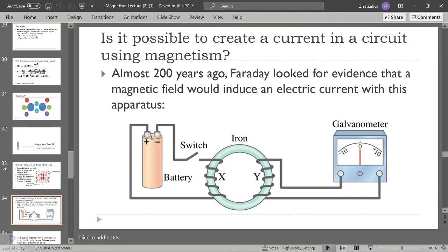So what is he doing here? Well, he's using the battery to push the current. The current comes out of the plus end, loops around a couple of times, and then goes back into the negative end. But we know from the last lecture that when you do this by looping it around, you're actually multiplying the magnetic field that is produced by the wire. And so you're creating this, which is actually an electromagnet. It's a solenoid. A solenoid is just the looped wire, but now that we have iron inside the solenoid, it's an electromagnet. So by doing this, we're producing a magnet.